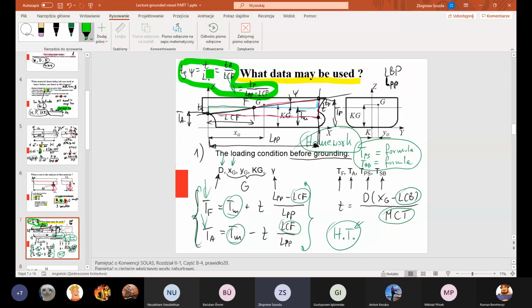And I encourage you and everybody to take a blank piece of paper, colored pencils in blue, green, and red. Mark the triangles I'm talking about, mark all the distances and angles, and develop by your own the formulas for calculation of fore and aft draft.